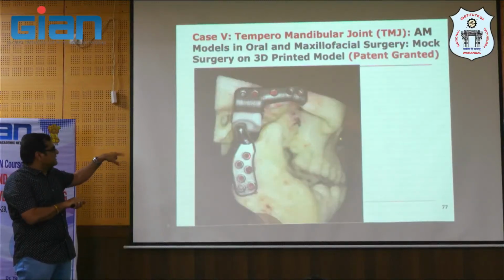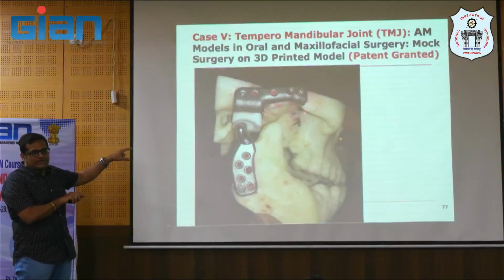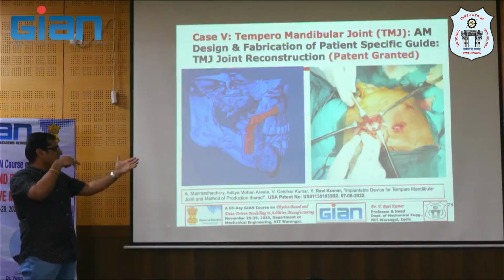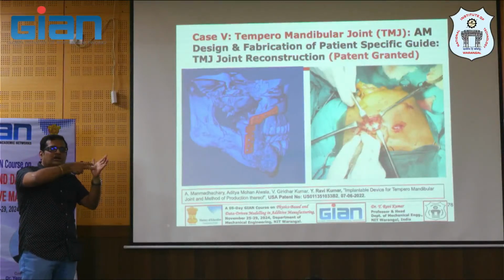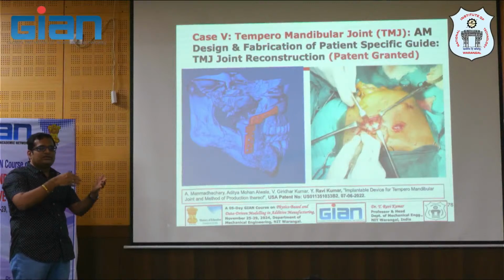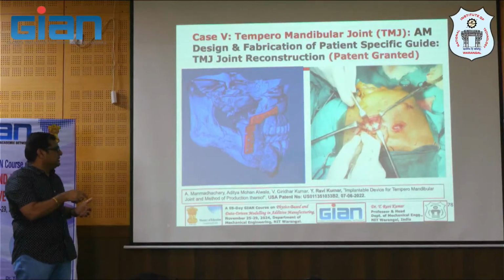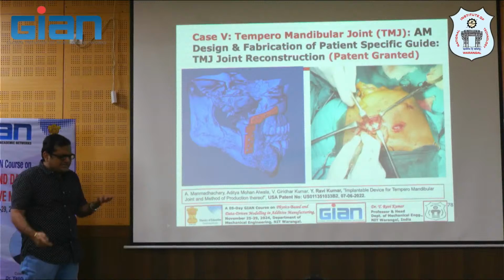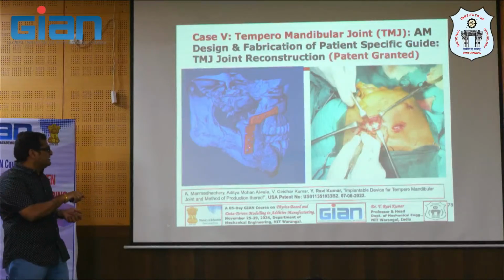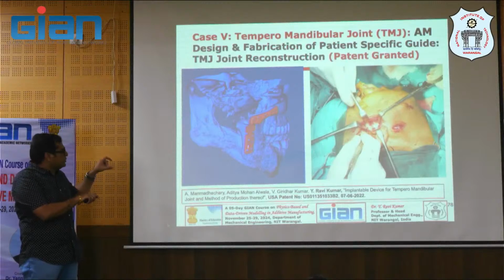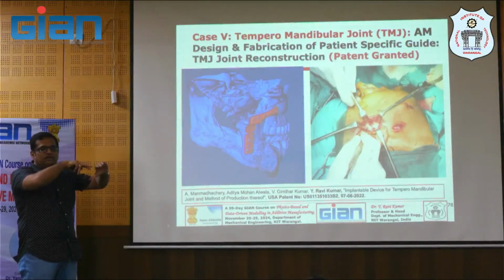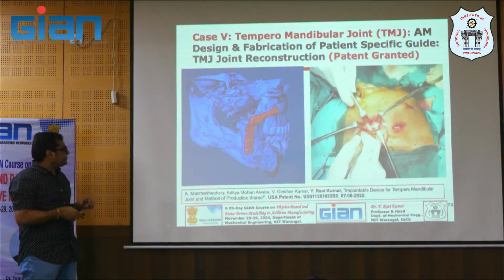This is a prototype, and this is the implant, which has been printed in titanium 6.4 powder bed system. And we design a template also. Why? Because the surgeon has to drill a hole and fix the screws, right? Just like that, he or she cannot drill. It is patient specific. They will get standard templates also, but that won't work out. This is a patient specific requirement. So this is the template design, and with the help of that template, they will use their drills to fix the screws, right?